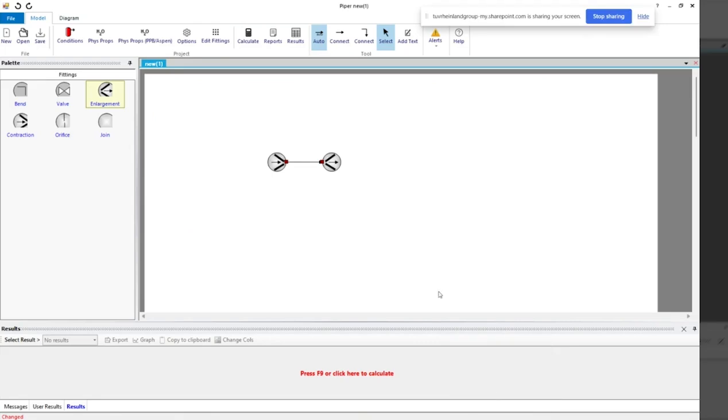What we'll find is that the API is making some assumptions. That particular sheet is assuming you're doing an isentropic flash through that valve. If you use the normal API 520 equations, it's assuming an ideal gas. We're making some assumptions around the orifice and KDs. And of course, Piper has its own correlations. So we're not going to get these things exactly right. We're just trying to mimic that relief valve.